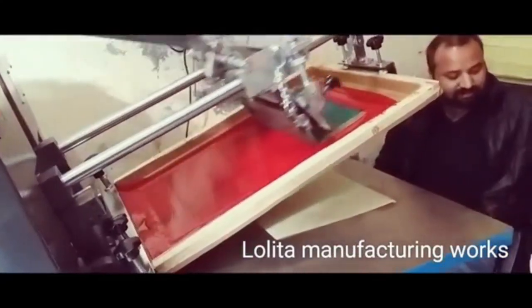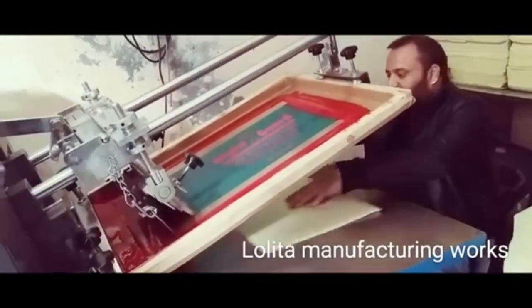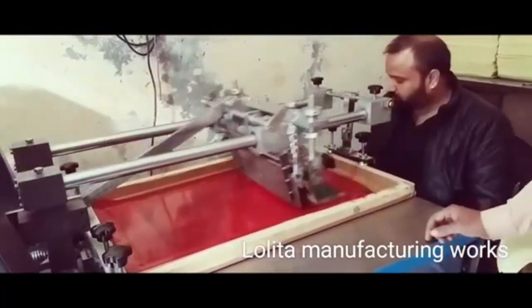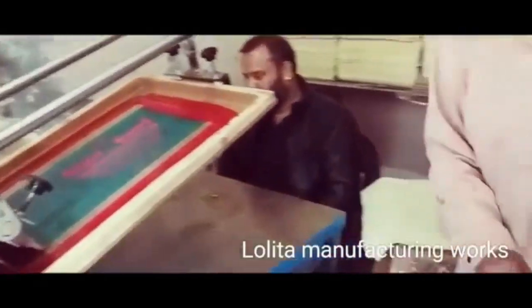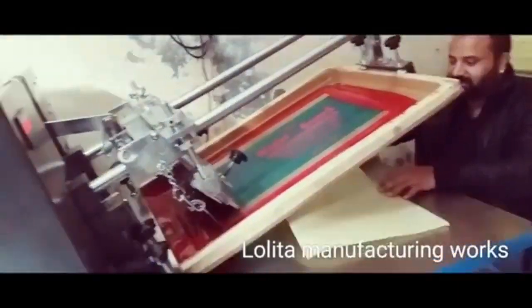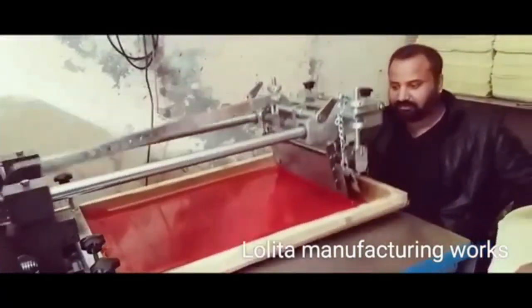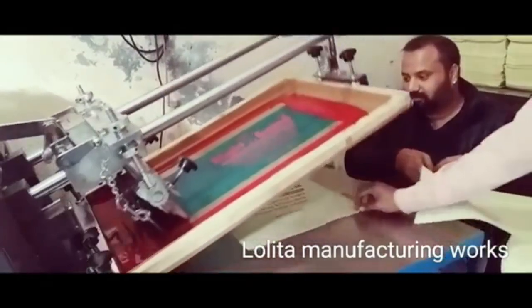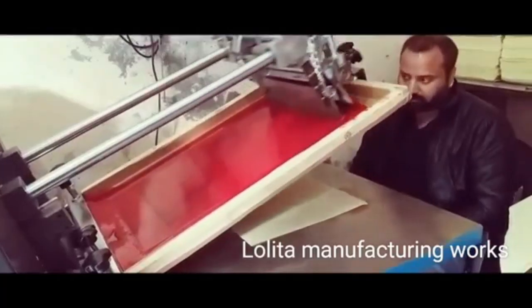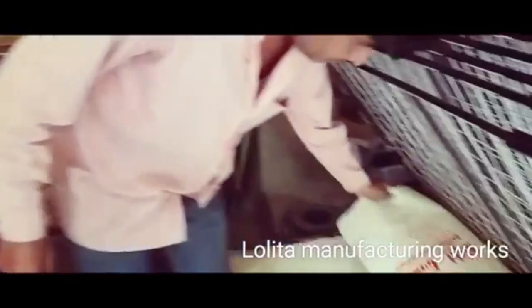However, for now, you just need to notice why we are calling this process a mechanized screen printing process. You can see in every cycle, the squeegee is dragged at the same speed and of course with the same pressure on the surface of the screen. That's the flooding stroke and that's the printing stroke. Printing stroke means the stroke of the squeegee in which the print paste flows through the screen. So this is the mechanized screen printing process.